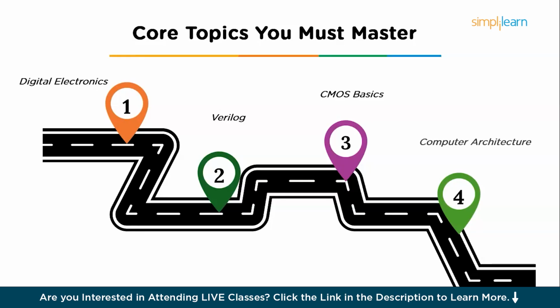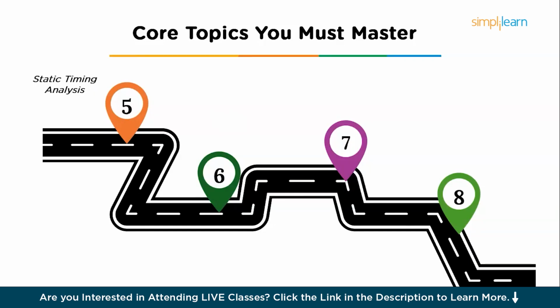Next up, we have computer architecture. Ask yourself, do you really know how a processor fetches, decodes, and executes instructions? This isn't just academic, but it helps you write better code and debug real hardware issues. Next up, we have static timing analysis or STA. This is where a lot of candidates struggle. So don't try to memorize formulas blindly. Understand concepts like setup and hold time, clock skew, jitter, and uncertainty. Once you feel confident, jump straight into solving timing problems, questions that always come up in interviews.